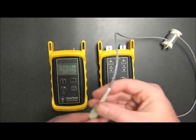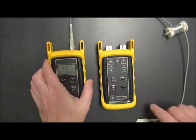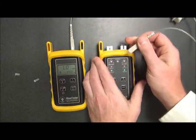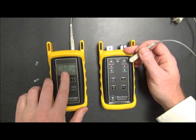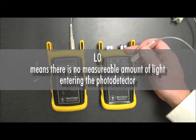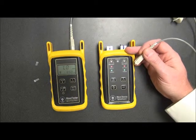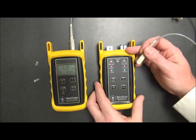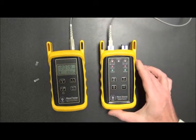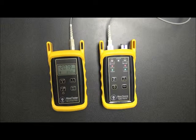Now, with this cable, we're going to check this one again, and again, we want to make sure that it's still reading around minus 20 dBm. And one thing I'd like to point out here is the fact that you see the word low here. What low means is that there's no measurable amount of light coming into the detector. This is because we haven't connected anything in yet. You'll see that when we connect in here, we will get a power reading. Okay, in this case, we have a reading of minus 20.79.